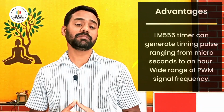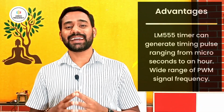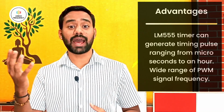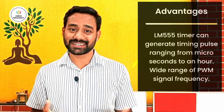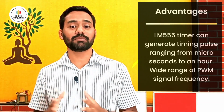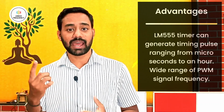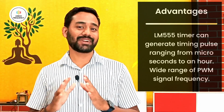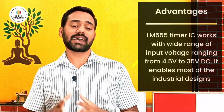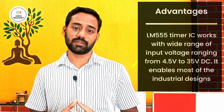Here are 5 important advantages for consideration. First one is the LM555 timer IC can generate timing pulses ranging from microseconds to an hour. You can literally generate a signal as fast as microseconds, and also a time pulse as long as an hour, which is awesome and very suitable for various applications in this category.